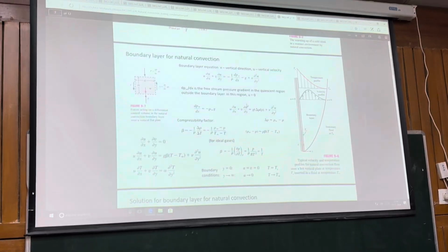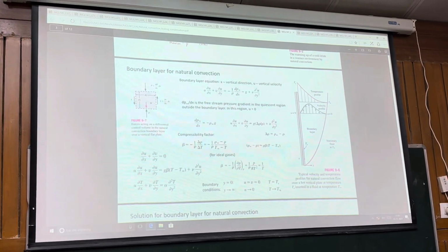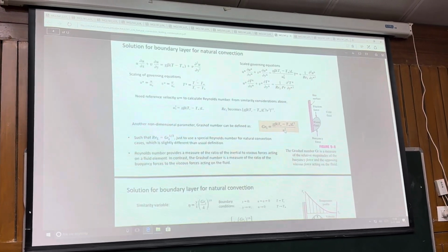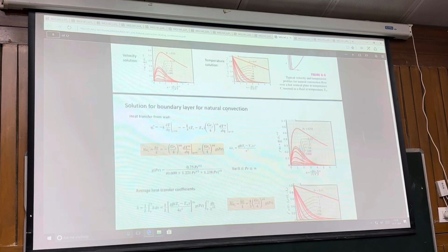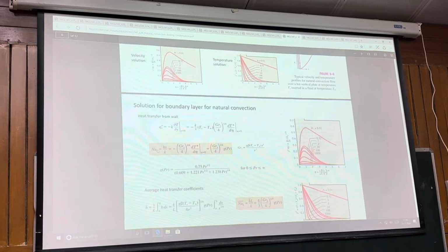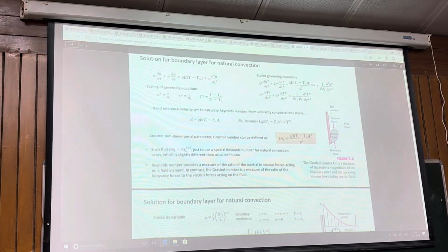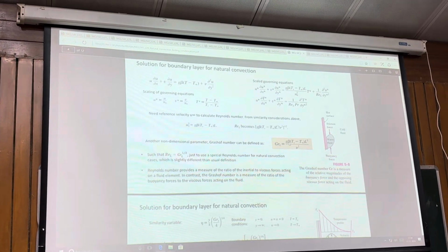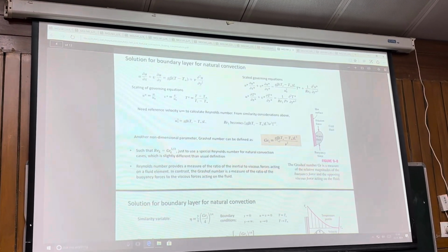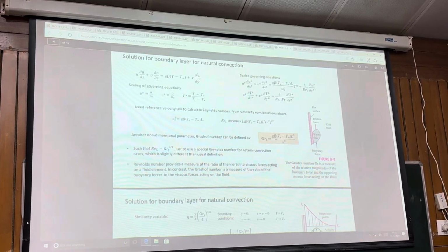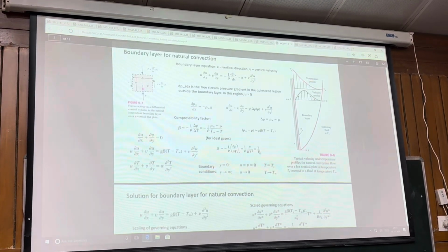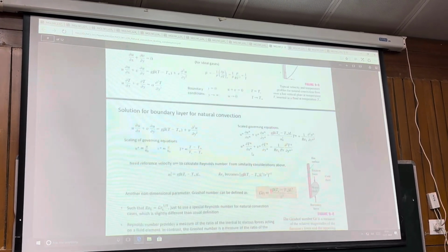Natural convection, again, these equations will not be there. You should know the Grashof number and how to use the Grashof number to obtain the Nusselt number. Okay. So for the Grashof number, properties are there. Beta is 1 by T. That will not be told in the exam. You should know, beta is 1 by T for gases, and that you should know.